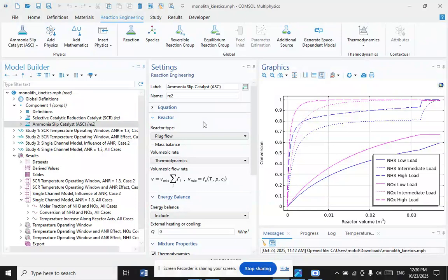The quality of the fuel also influences the formation of these particles. For example, a high sulfur content diesel produces more particles. Lower sulfur fuel produces fewer particles and allows use of particulate filters. The injection pressure also influences the formation of fine particles.